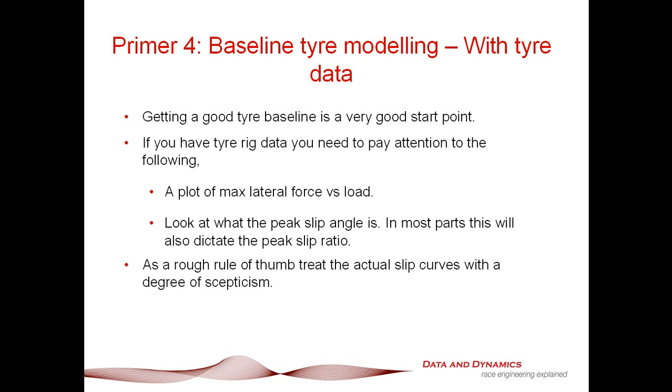Now, in a lot of tire data, you'll actually be getting plots of slip angle versus tire force for various loads. What you want to be doing is looking at where the peak values are for those curves, and that gives you your baseline tire curve. Now, let me state very, very directly here, it's a start point. It is not the end.